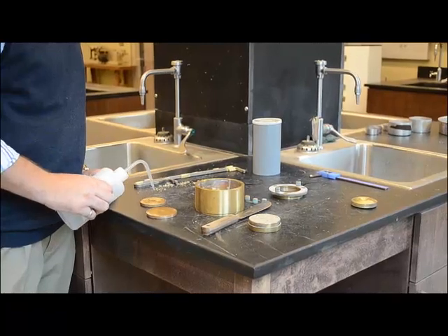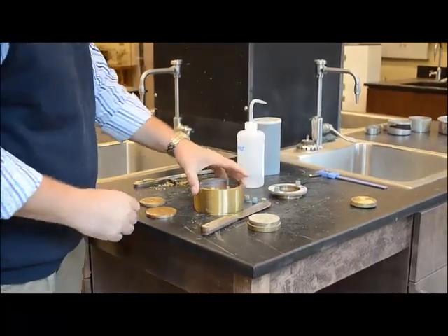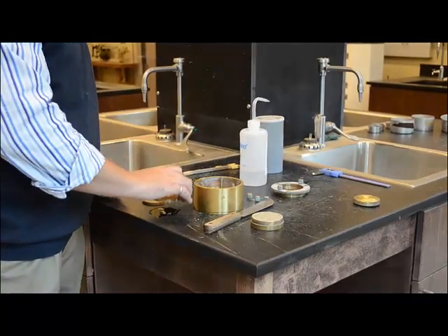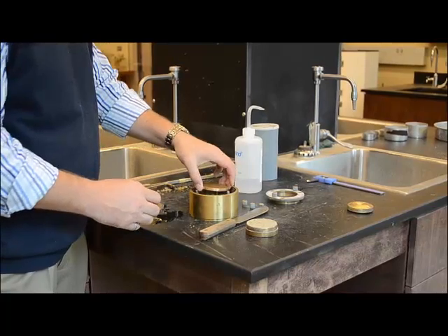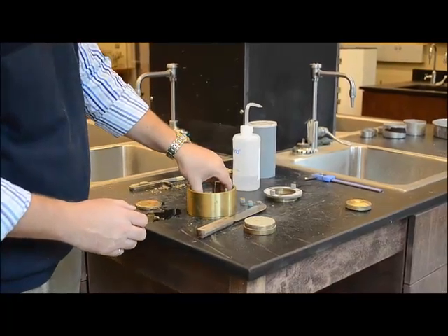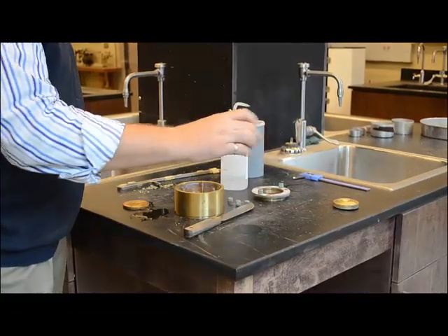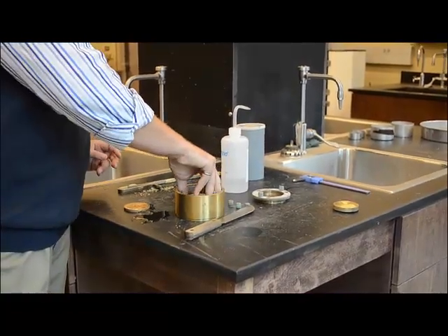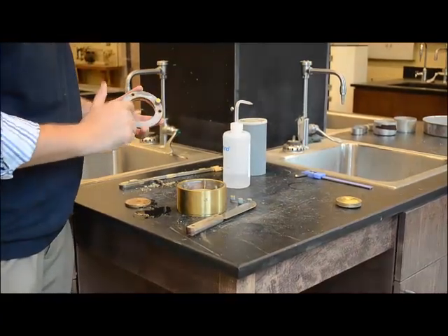Now we're going to do the top porous stone as well, because that stone has a lot of pore space in it, and we want it to be filled with water and not air. Sometimes it might take a little bit to get through, but we'll go ahead and place that into the water bath. You want the rough side against the sample itself. Then place your soil sample in with the thinnest part of the cutting ring at the top.